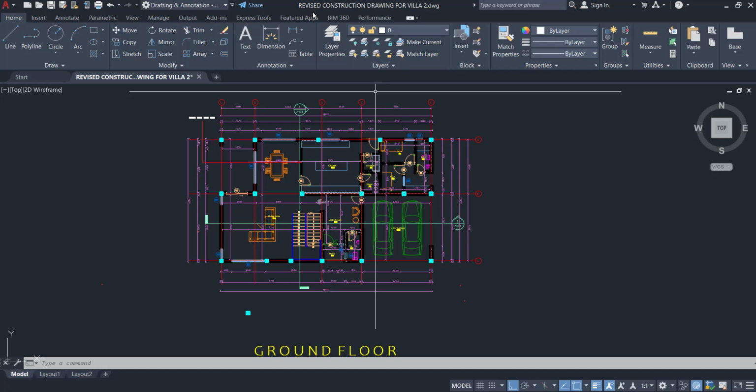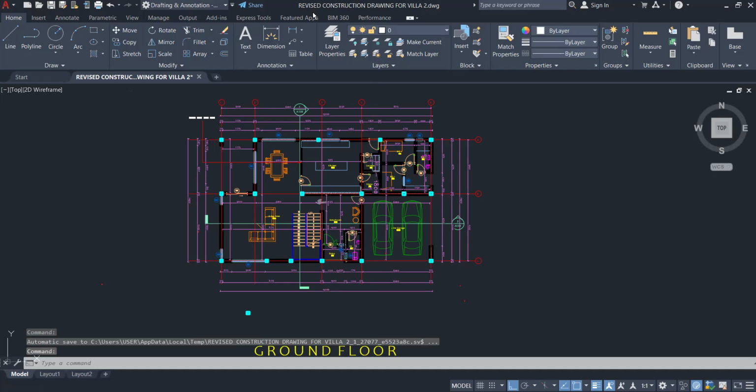Like this design now, if I want to do it for a client that I know does the work, everything I provided, they are going to do it, I will do the GA. But if it's some client that I know will not pay, I will break it down in such a way that all my reinforcement is going to be 16 mm. I will not have any 20 mm. Because when some clients see a design and they are seeing 20 mm bars, they'll be upset.